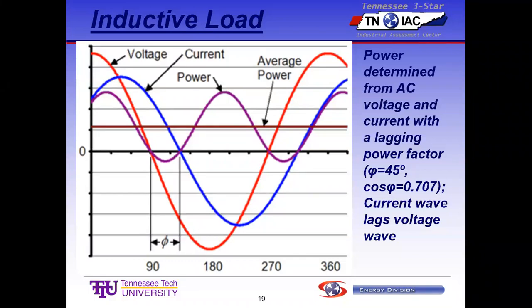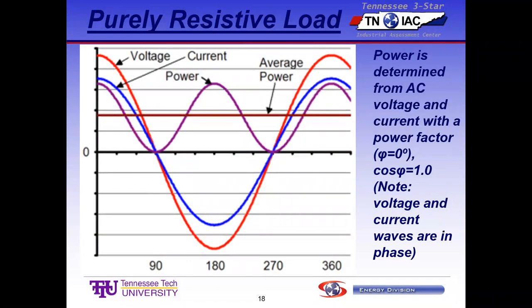Okay, so this is where we left off before. At the previous slide, we saw where power factor is 1. Basically what we're saying is all of this voltage and current are in phase with each other, which means that they peak together, they go through 0 together, and so the positive peaks and negative peaks all occur in phase. That's characteristic of an all-resistive load, and as far as the power factor discussion is concerned, that's the best, the most efficient use of the electricity.